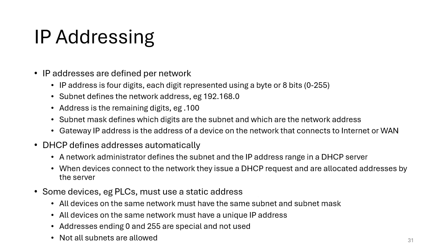Now, if you're using a PLC system for performance, you probably will need to define IP addresses because PLCs don't normally have automatic addressing. There are some mechanisms like BootP, but they're rarely used. So normally that means that someone has to define the network and configure those IP addresses. And there are local type networks.